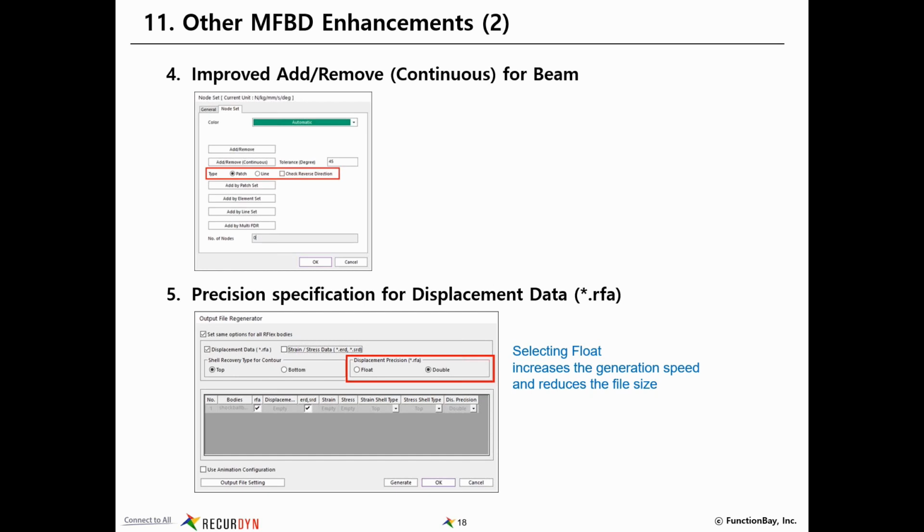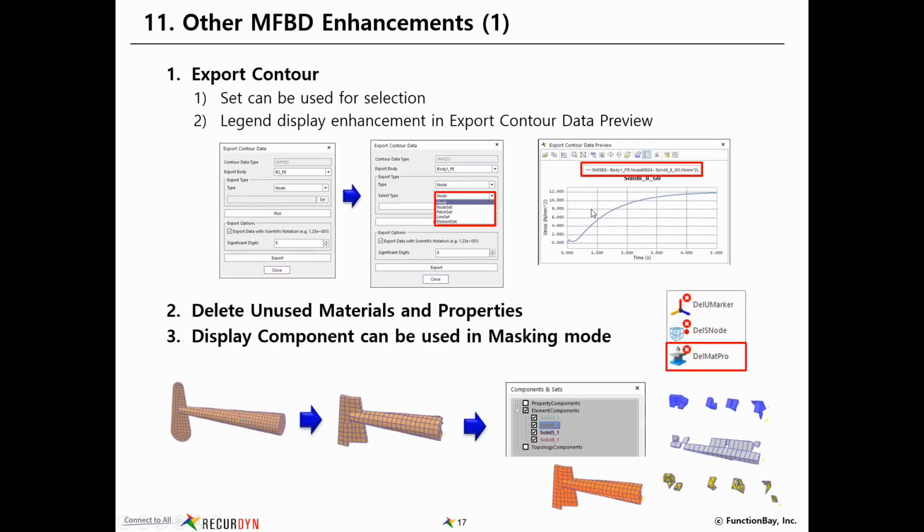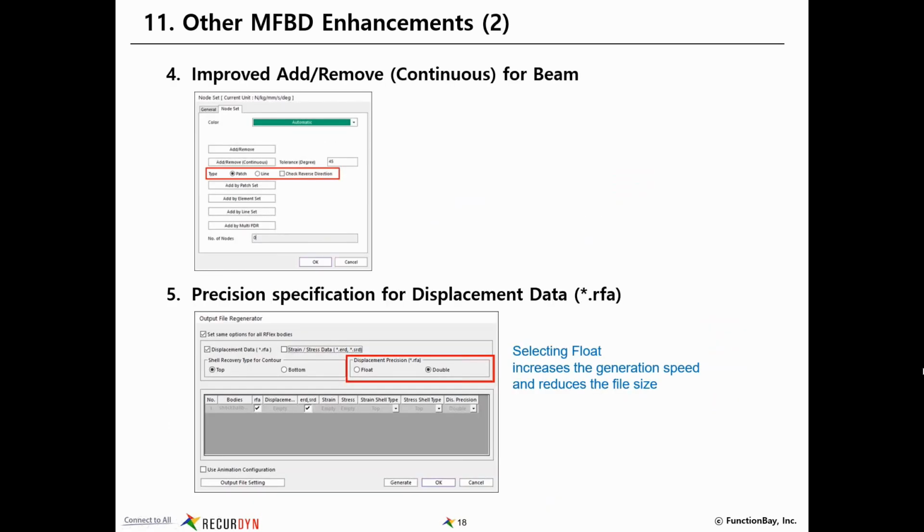So top defines the bigger radius, something like that? No, it has to do with the direction of the normal. When I'm using something like that, I'll just try both options and look at which way it's bending, and I will know if it's going to be in greater tension on one side or the other. You can go back and look at the surface normal, but you can also just inspect the value of the stresses and figure out which way it's going. Okay, thank you.